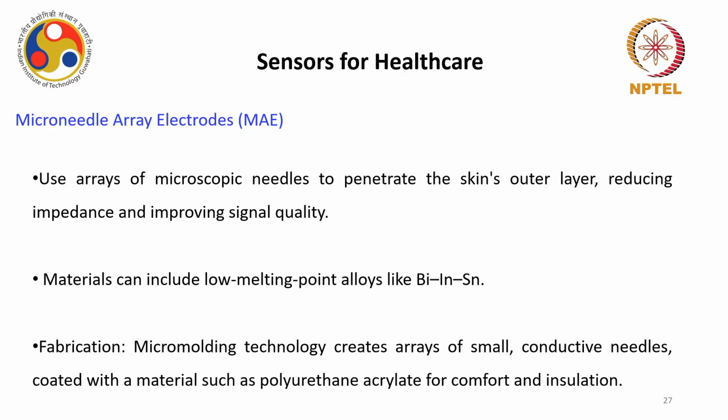The materials for these electrodes can be any low melting point alloys, and they can be fabricated by simple micro molding technology, or nowadays patterning is also possible for these electrodes using a simple SU8 kind of polymer, the photoresist, in a photolithography laboratory also.